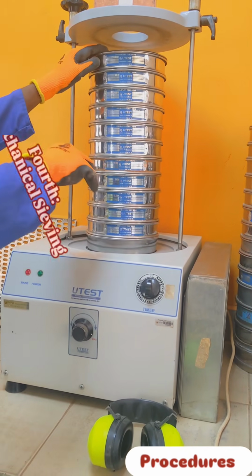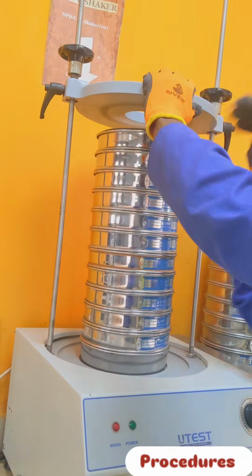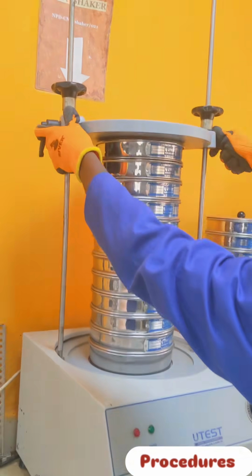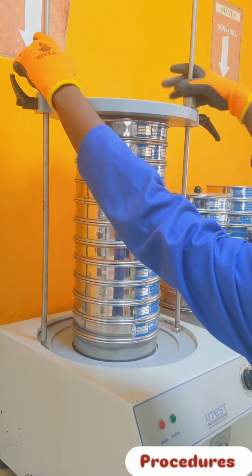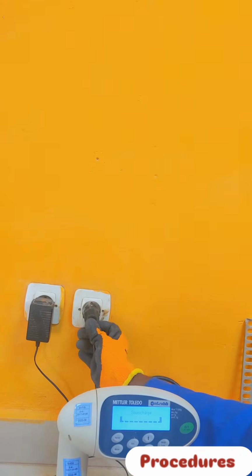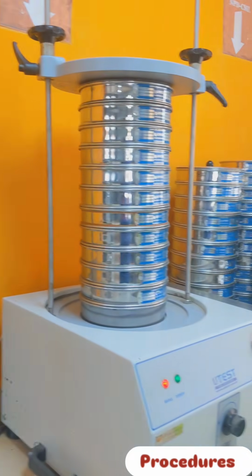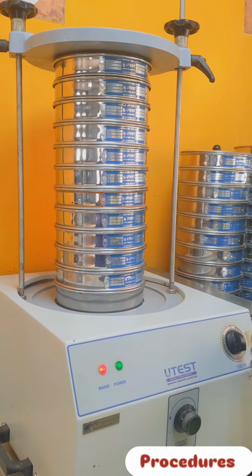The fourth, mechanical sieving. Place your stacked sieves into the mechanical sieve shaker and fix them securely in place using clamps. Then connect the machine to the power, but before switching on, protect your hearing by putting on your earplugs. It is going to get loud. Now start sieving for 10 to 15 minutes as required by the standard.